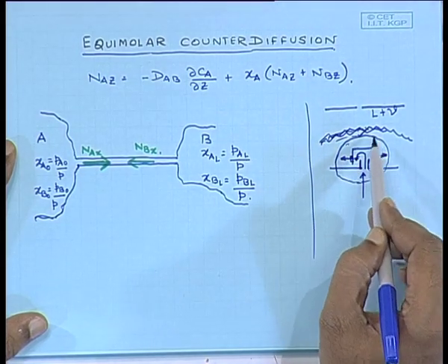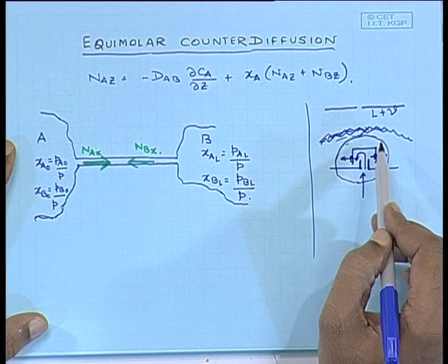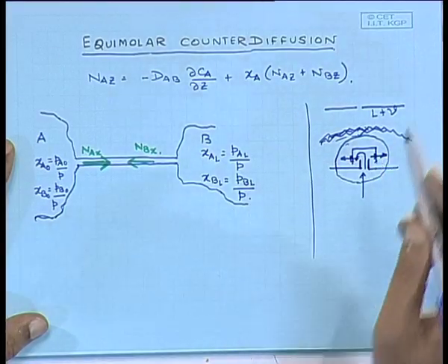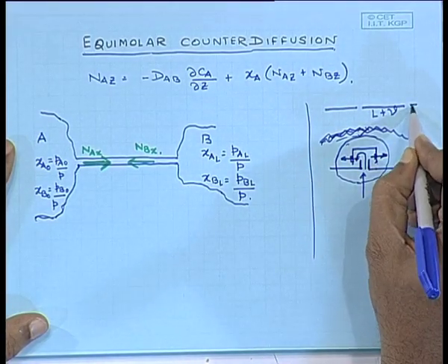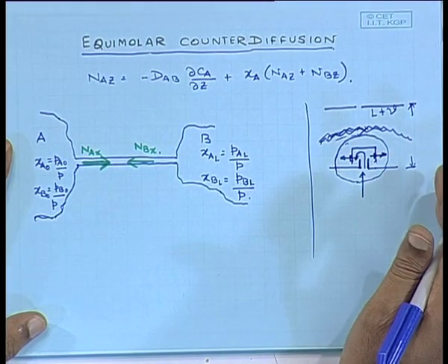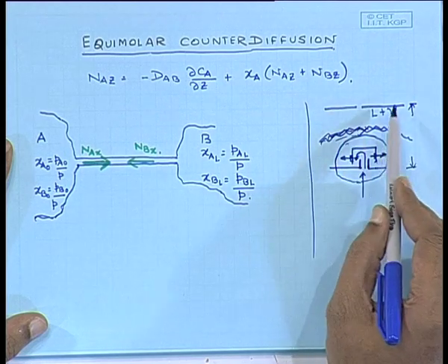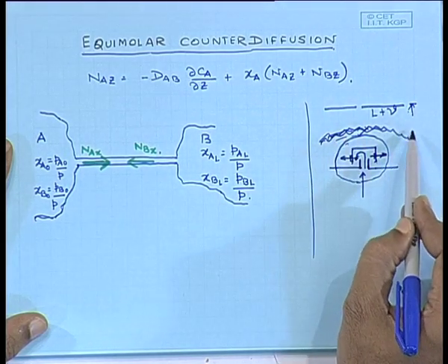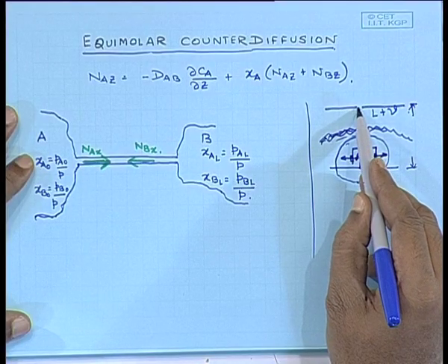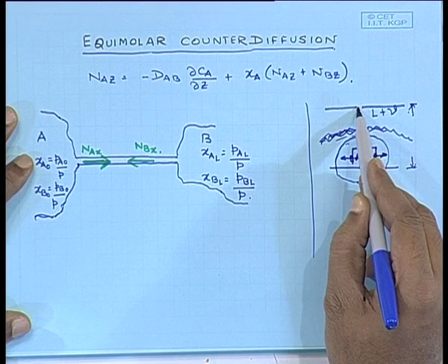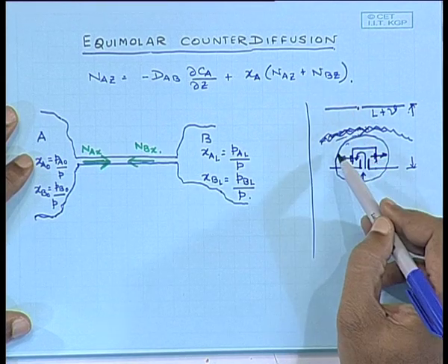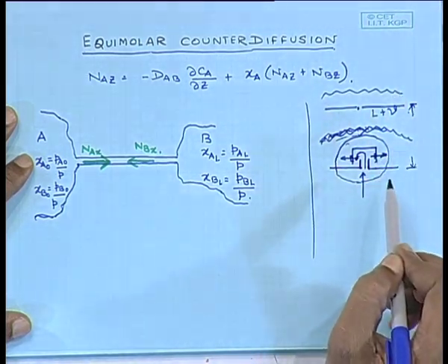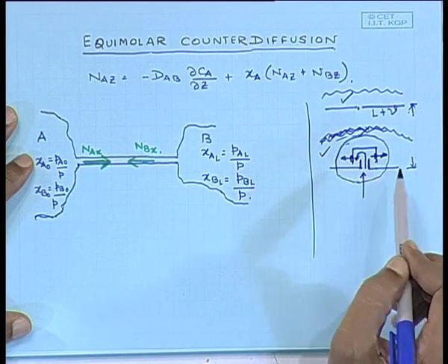Now, if this liquid is very foamy, it forms foams very easily, then there is a danger which we will have to think about as well. Now, what should be the separation between two such plates or stages? If it is a foamy liquid, would you like to provide more distance between the two stages? Obviously, because if the foams reach over to this one, then what you are doing essentially is short circuiting one stage, because over here there should be another liquid pool, and the concentration of this liquid pool and this liquid pool should be different.